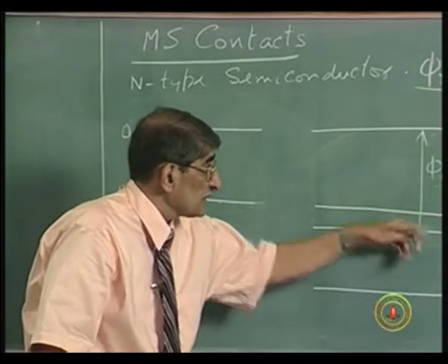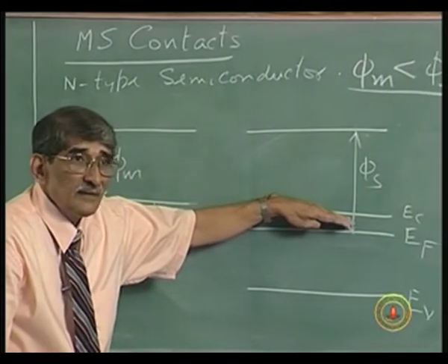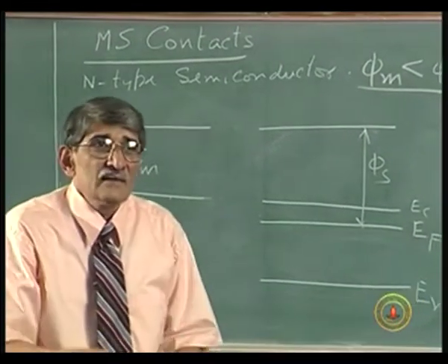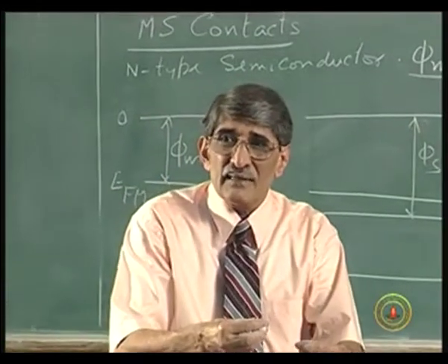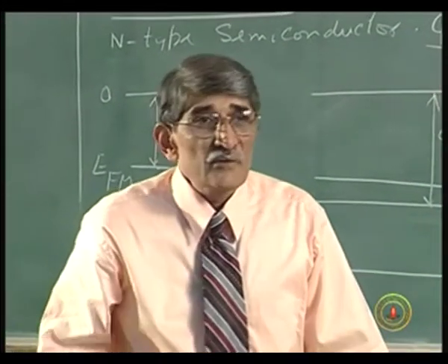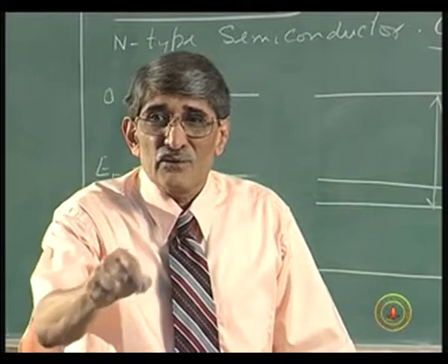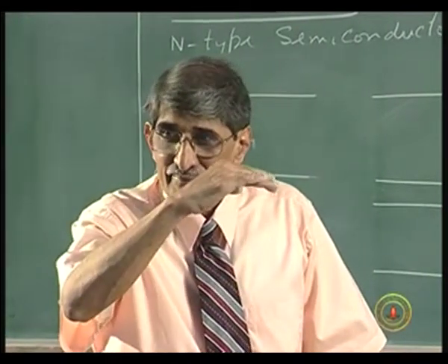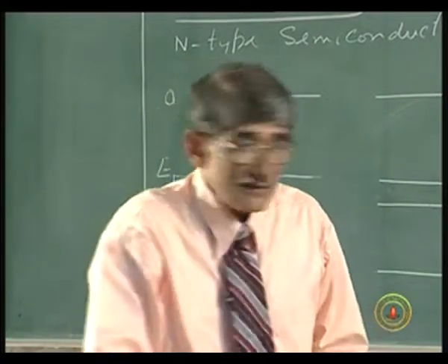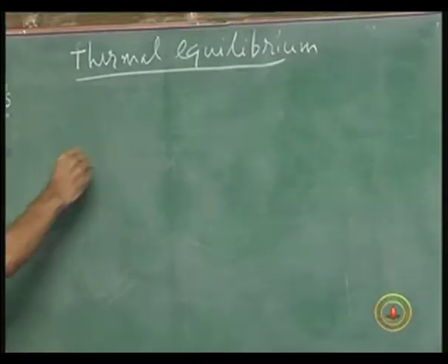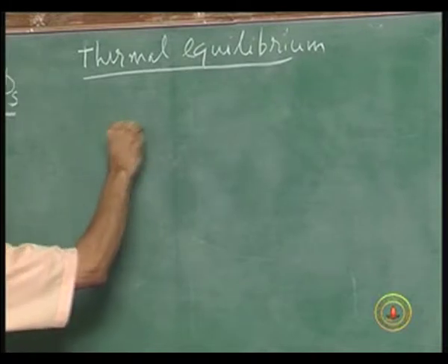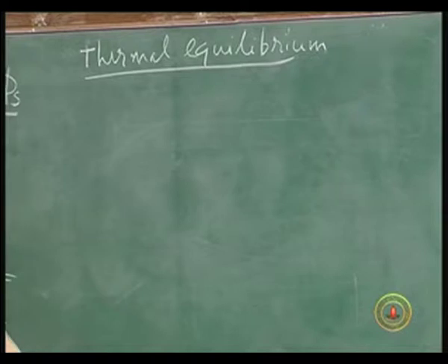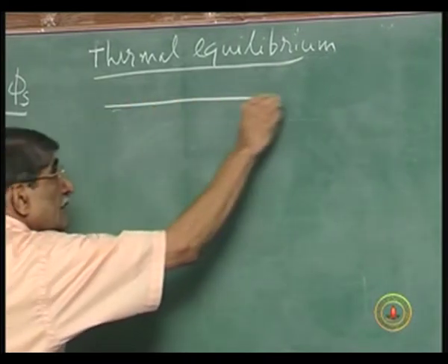So, the neutral portion here, the energy band diagrams here will actually go up, difficult to if it is negatively charged, when you take an electron near that, it gets repelled. That means you have to spend more energy to take the electrons to that point. So, once it is negatively charged, the band diagram will move up. Okay, that is the key thing to understand. So, now when you form the contact here, you draw it a bit up there, so that there is space. So, that is thermal equilibrium.